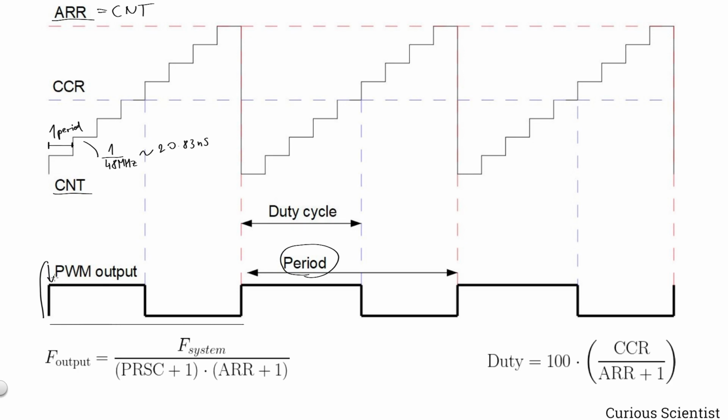And then when the counter, so this guy here, reaches the value of the CCR, so basically this is true, then the PWM output flips signal. In this case goes high to low. And then it continues until it reaches the condition right here, and then it starts over. And then you created basically the PWM signal, the periodic PWM signal.